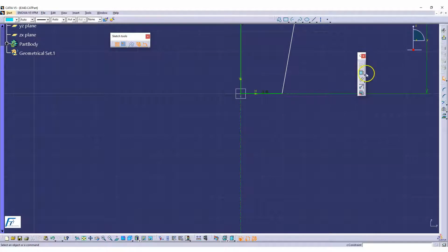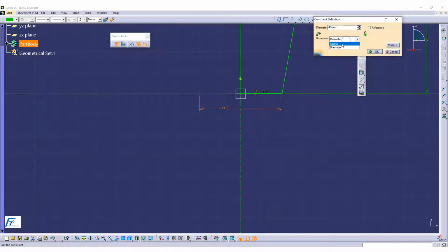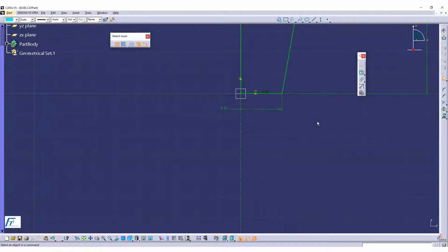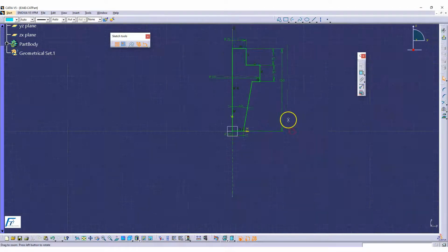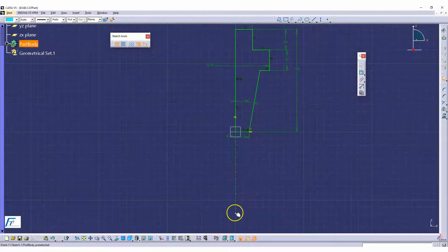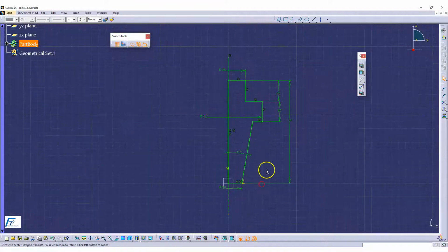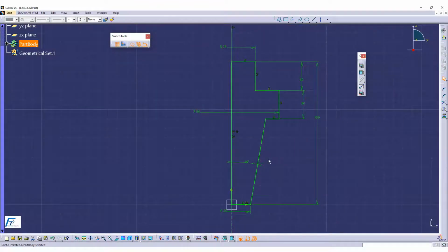So that means I'm going to select this point and this one with reference to this axis, right click and go with the radius. Just double click on it and give the radius value. So this indicates that you're giving a radius value. Always understand that when you start creating any axis system and cylindrical component, the representation of your geometry, the dimension, is very, very important.